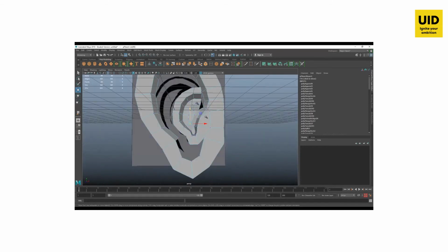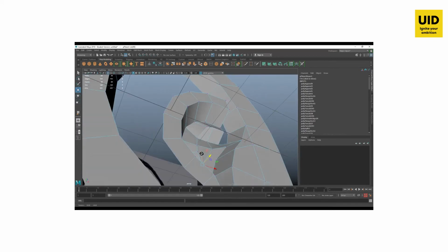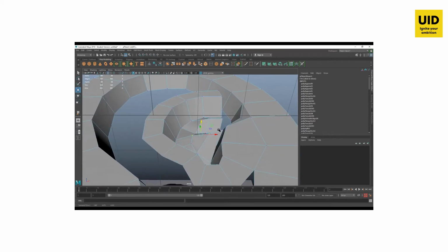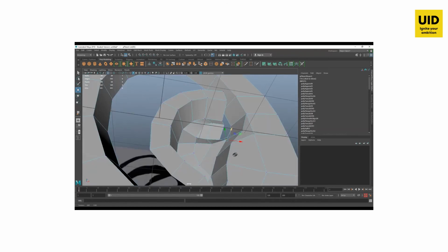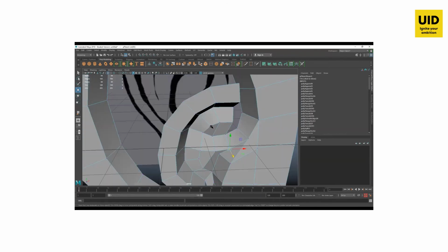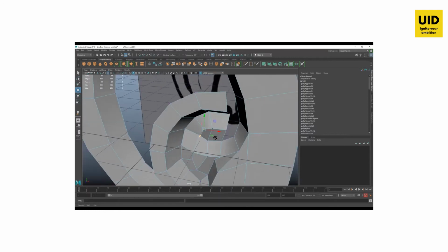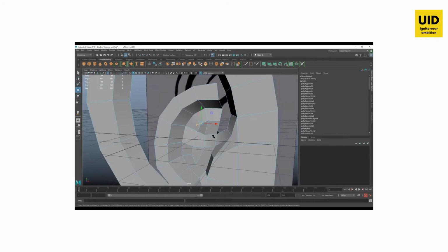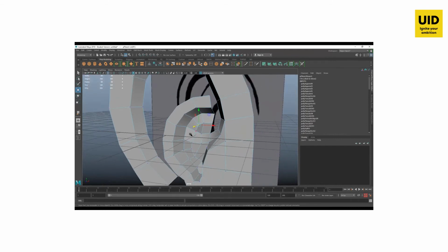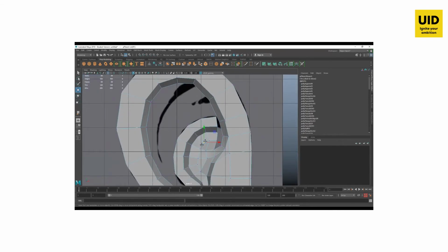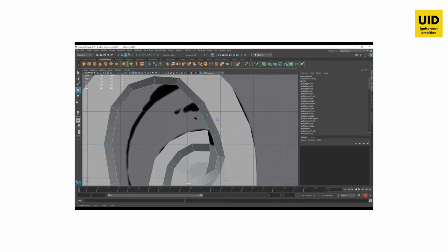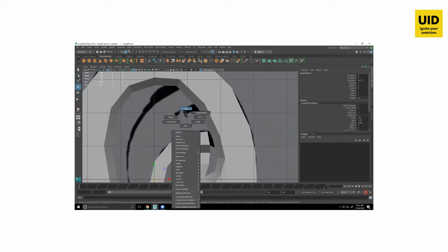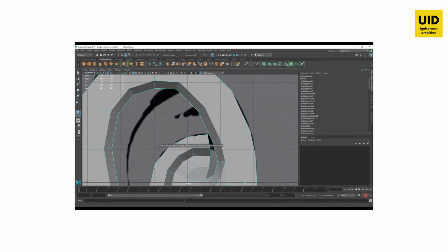This is what we have till now. Pull it up a bit. Okay. Now let's fill in the big gaps. Go to my edges. Again, I'll go to my append poly tool from here to here. And so Y to repeat the last tool. Enter. Y.